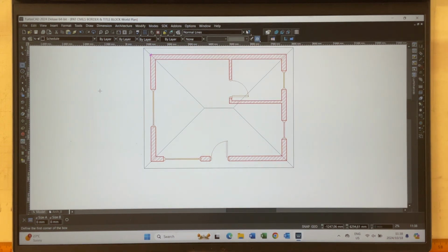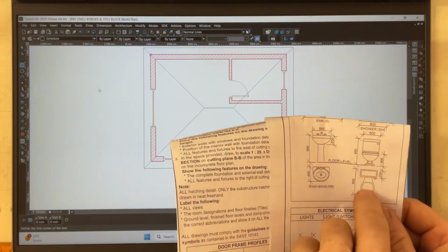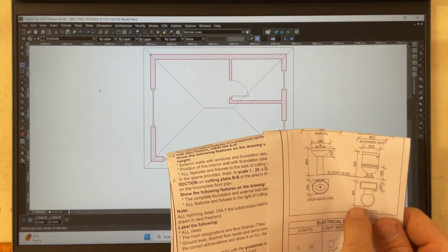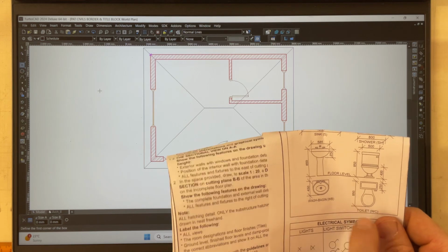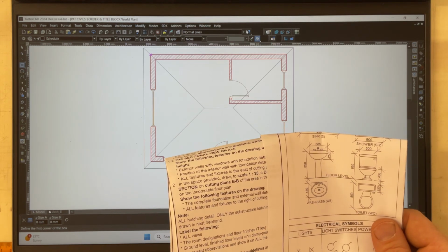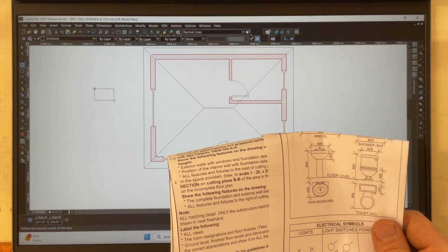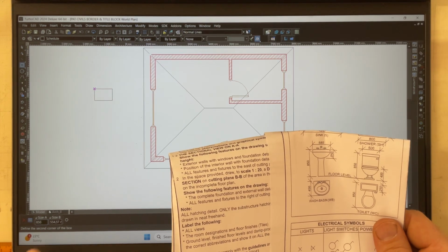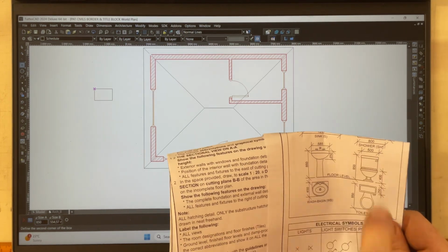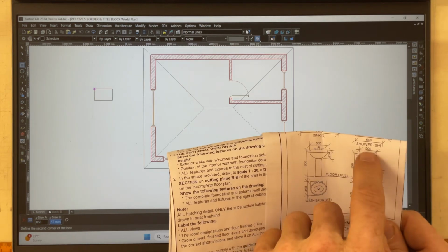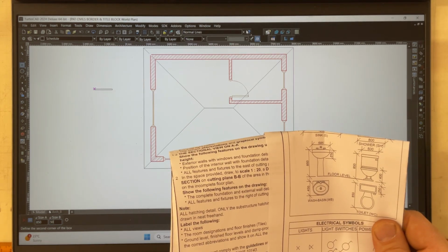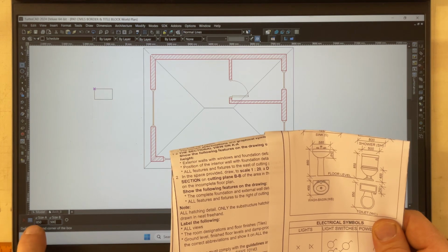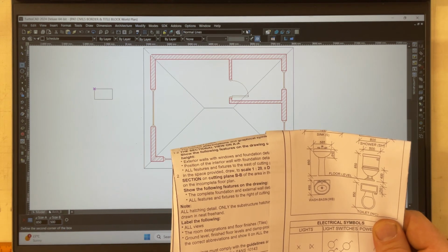Right, they've given you some dimensions on this sheet over here of the toilets. Okay, there is my toilet dimensions, and it says that it's got a length over here of 850 millimeters. So I'm going to first of all select that little rectangle over there, click over there, and I press tab, 850, and the width of it is tab, 500. You can see where those 850 there, 500 there, press enter.